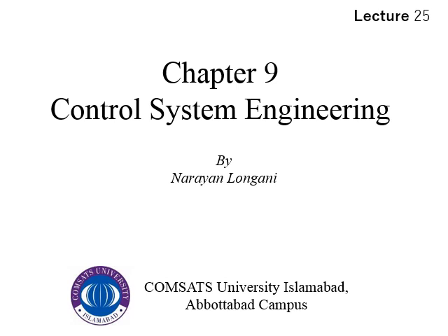We are studying a chapter of System Design with the help of root locus. In the last class, we studied about Introduction to Controllers, Ideal Proportional Integral Control, and Lag Controller. The PI or lag controller is used to improve the steady-state error. With a PI controller, we improve the type of the system and achieve a zero steady-state error, whereas in the case of a lag controller, we improve the steady-state error by a factor.